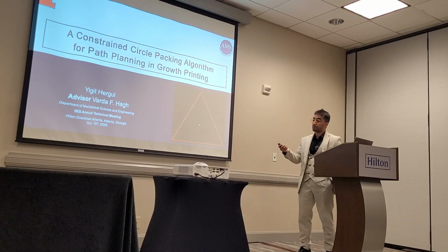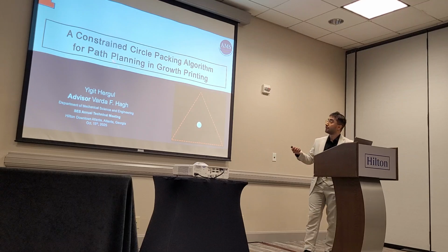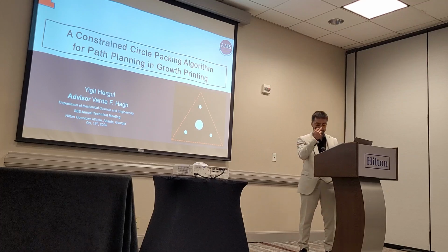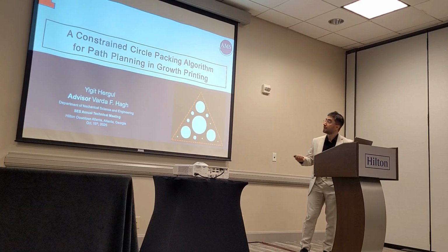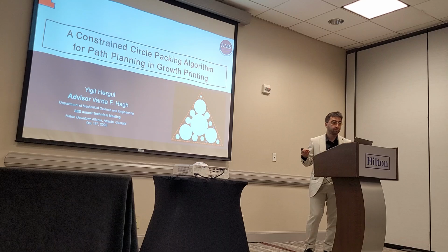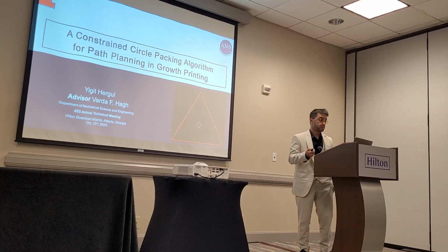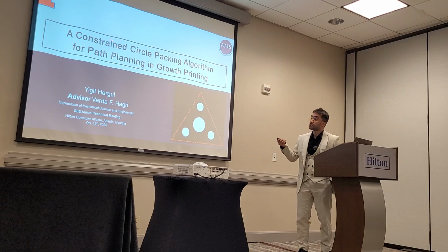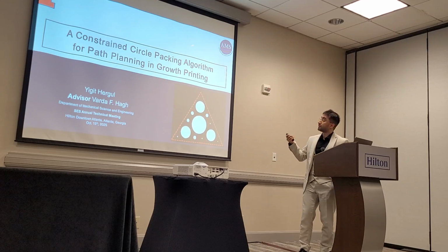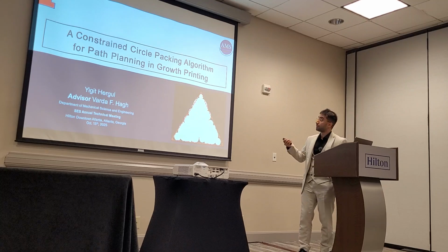And today we will be talking about a constrained circle packing algorithm that we are developing for path planning in growth printing. Growth printing is actually a new additive manufacturing technology using polymers. And we are trying to create a path planning for this manufacturing technology because it requires certain constraints on the system. So the way to do this path planning is to solve a circle packing problem, which is very constrained, so we are developing an algorithm, not strictly restricted to growth printing, but very useful